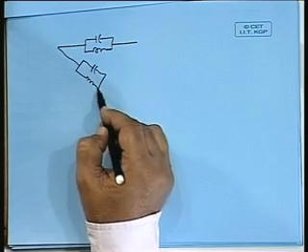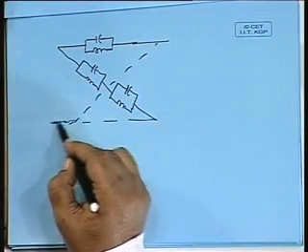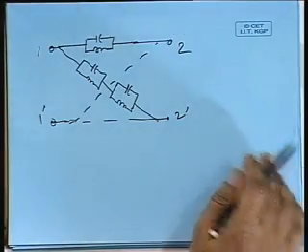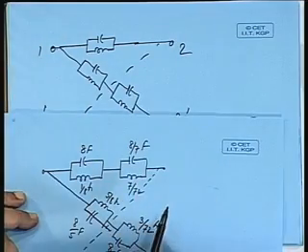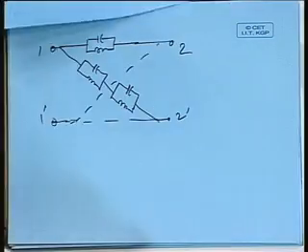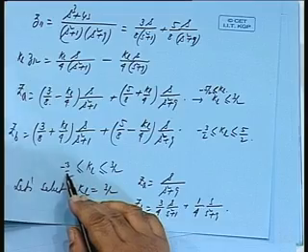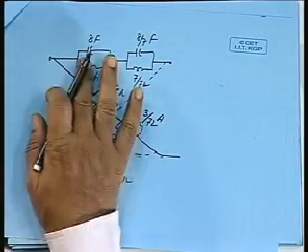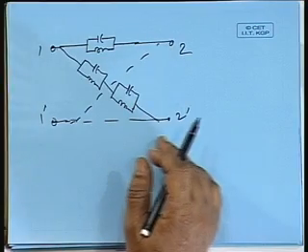Is that all right? You can calculate their values. See, earlier we had one parallel bank here, again another tank circuit here, and again here a similar element will be coming. So, these we are eliminating by taking KL equal to that limiting value, one of the limits. If you take KL equal to the other limit, minus 3 by 2, then in ZB this will get eliminated. So, ZB will have one less element, whereas ZA will have two elements. So, this is how you realize the networks for ZA and ZB.